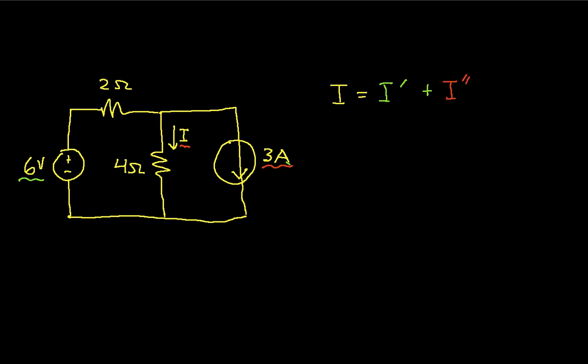For example, when we design amplifier circuits, and these amplifier circuits use transistors or other solid-state devices, quite often it's useful to think of a DC biasing voltage due to a DC source, as well as an AC or signal voltage, which is due to a signal source.